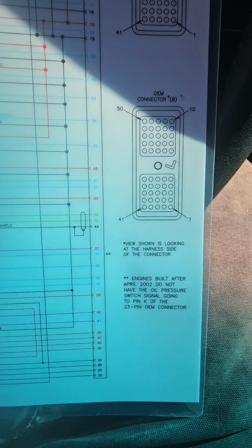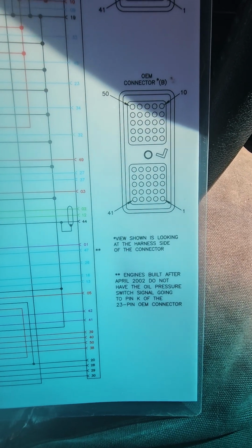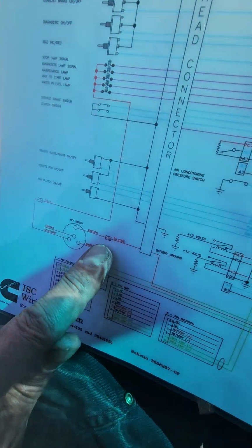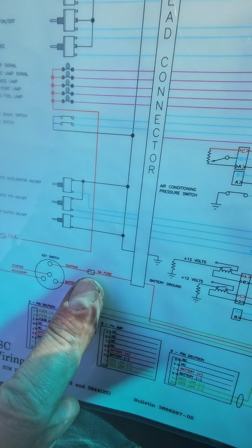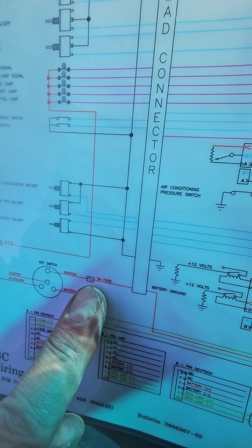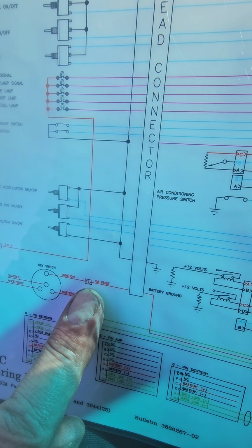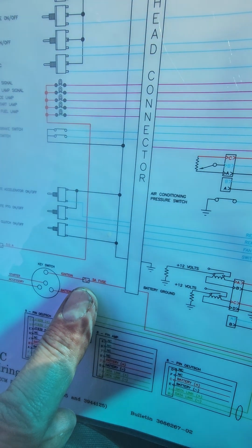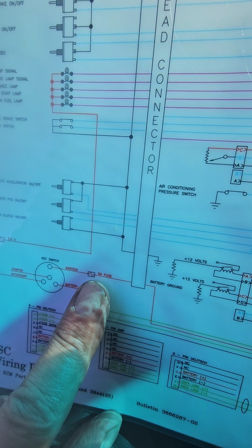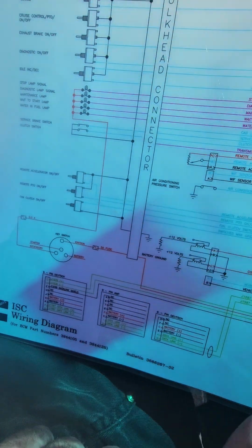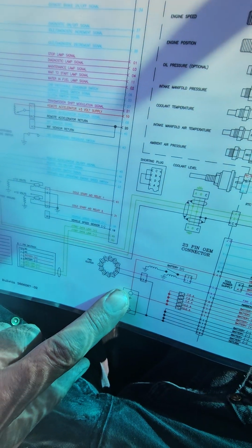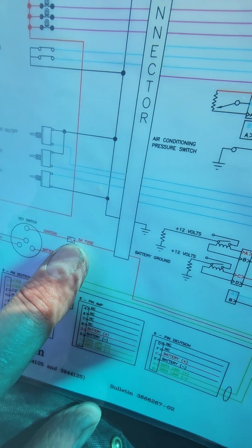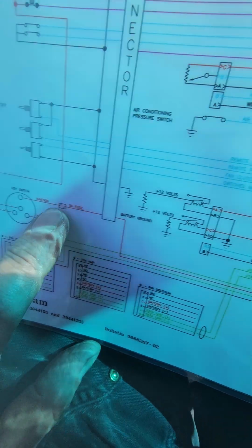So when I jumped in the engine compartment and tested that, I was like, wow, cool. Because this is an easy fix. Like, we're going to check the fuse, and if that doesn't give me the solution, I'm actually going to create a new ignition switch signal and have a healthy relay creating an ignition signal straight from the battery in the engine compartment. But first things first, I'm going to pull this guy and see if I could figure out if this is a corroded fuse.